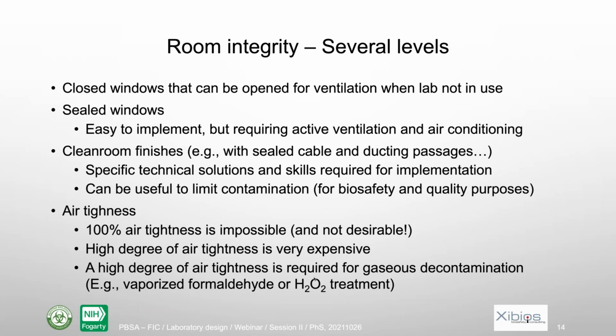Then the highest level of room integrity is air tightness. First thing is that 100% air tightness is not possible, and it's not even desirable because you could have many different drawbacks. Also, even to reach a very high degree of air tightness, it's very expensive because you need to pay a lot of attention and find technical solutions for everything, not just for the windows, doors, and so on, but also for each penetration in the lab. You need always to find something.